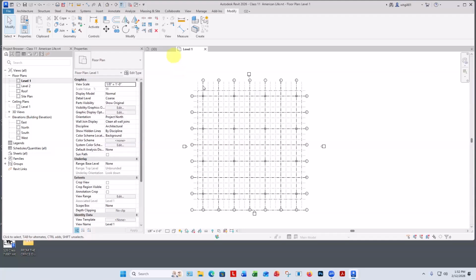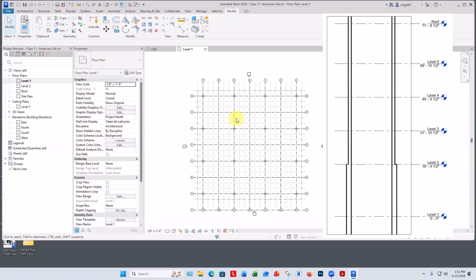We want to put the 2 building cores in here, one for elevators and one for bathrooms. And we need to see where they are. And let me tell you that as we look at this building, here's the plaza floor level, and then here are the others going up. As the elevator cores come down from upstairs, they're a certain width. When you get to the first floor and then down farther, the inside of the elevator shaft is just the same width all the way down. But the wall actually gets fatter over there, starting at the first floor and going down to the basements.